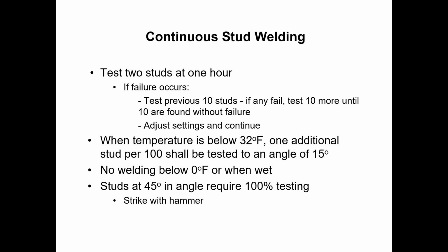Anytime you've got studs that are being stud welded into the crook or the crotch of an angle, so specifically, if you had a piece of angle iron and you were welding studs into the reentrant corner of that angle, that's a pretty common condition for a coping piece or something like that, 100% of those studs have to be tested. And the reason is it's just more difficult to get a good plunge, to get everything oriented correctly. So we're making sure we're testing all of those.